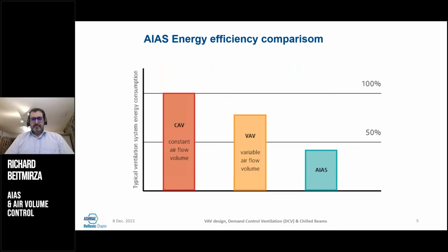We've seen some comparisons up to today. What we tend to say is when we use constant air volume is the highest energy cost. When we go to VAVs, we're able to reduce that cost based on the demand. And when we use programs, controllers, where it is optimizing the use or the demand, we're able to reduce the energy cost below 50%. This will vary market by market. This will vary building by building. It all depends on the design of each building that is considered.